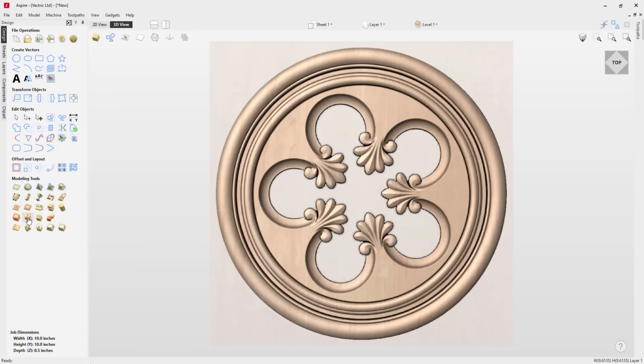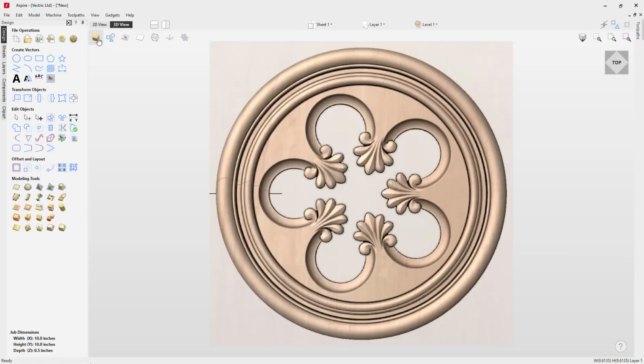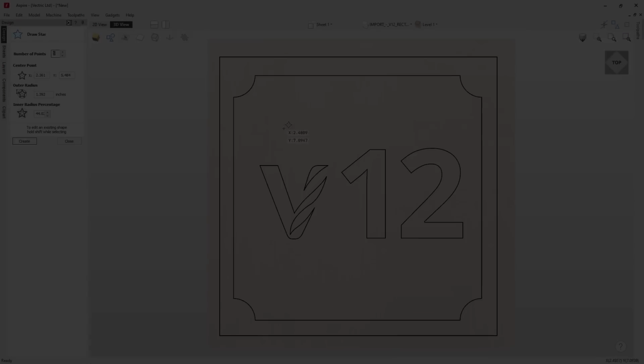The 3D cross-section tool allows you to quickly create vectors from any parts of your 3D model, which is perfect for model recreation. Simply click between 2 points and the vector representing the cross-section between these points is created and added to your project.